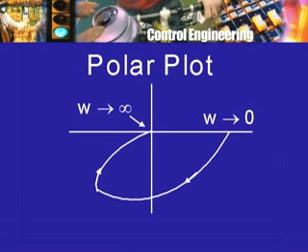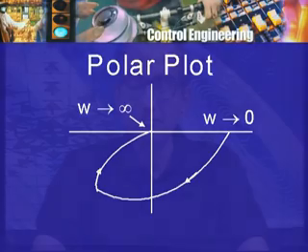And from this then we are able immediately to see that the kind of polar plot that I had sketched last time is correct. For DC, of course, there is no phase shift, but for very small frequency there is a phase shift, and therefore the angle is negative. The gain is of course not 0, not infinity, but it is some finite value. At very high frequencies the gain is very nearly 0, so I am near the origin, but the phase shift is not quite minus 180 degrees, it is an angle little less than 180 degrees in absolute value, and therefore this was the nature of the polar plot that I had drawn when we looked at the Nyquist criterion.